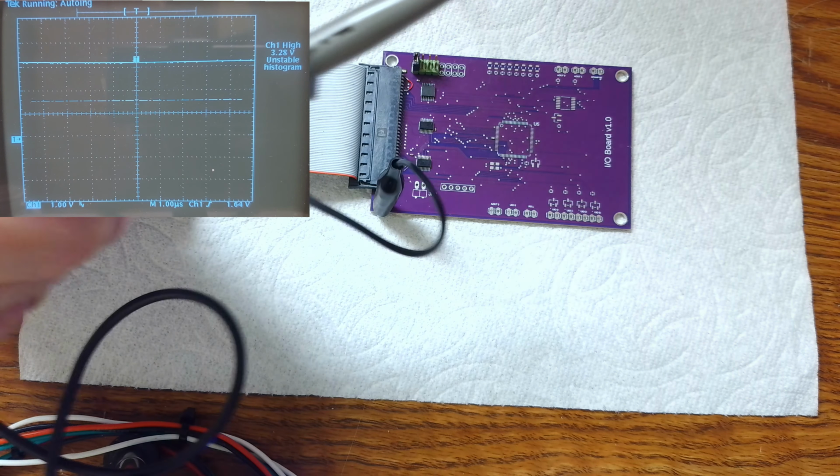So then these lines over here are address lines, and if you remember from the schematic, on this chip the inputs are being held low. They're hardwired low. So we know that if this chip is turned on, it's going to drive these signals in here low. All right. So when the chip is disabled or deselected, like it is now, then it's going to be in a high impedance state.